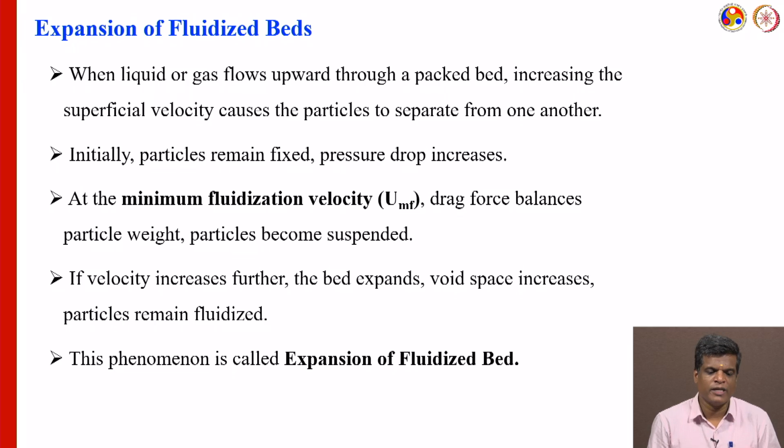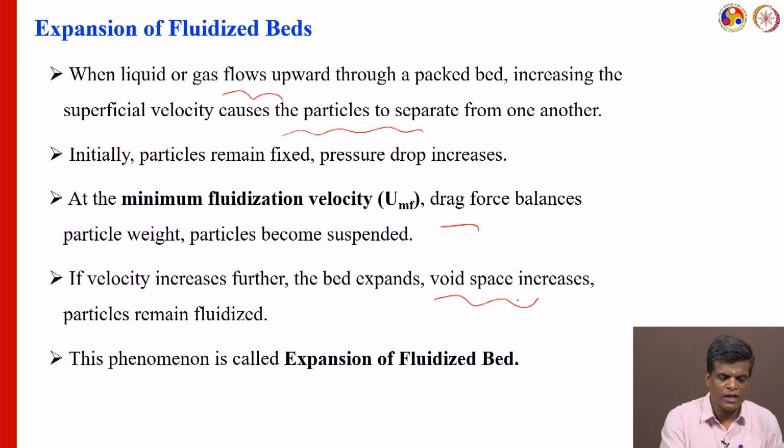So, what about the expansion of the fluidized bed now? If it expands, what will happen? When liquid or gas flows, the bed automatically expands and the particles separate from one another. Initially the particles remain fixed and the pressure drop increases, because that is a fixed bed or packed bed. Once the minimum fluidization velocity is reached, the particles become suspended. Then as the velocity increases further, the void space also increases, and the particles remain fluidized. That phenomenon is called the expansion of the fluidized bed.